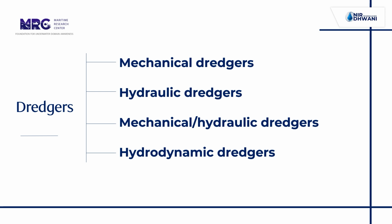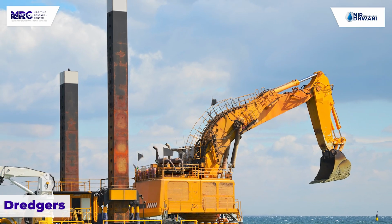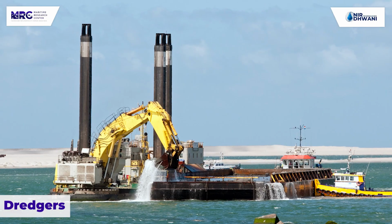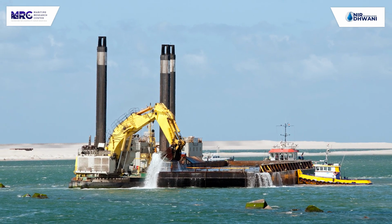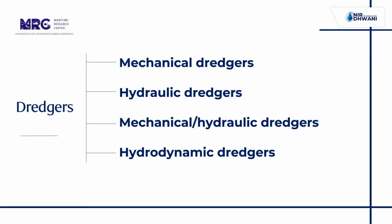Now, four broad classifications can be made based on the mode of excavation and operation. So there can be mechanical dredgers, hydraulic dredgers, or mechanical hydraulic dredgers which utilize both the basic elements in some combination, and then hydrodynamic dredgers. Within these four categories, further subdivision can be made on the basis of the propulsion, that is, those that are self-propelled either during the excavation phase, the transportation phase, or both.